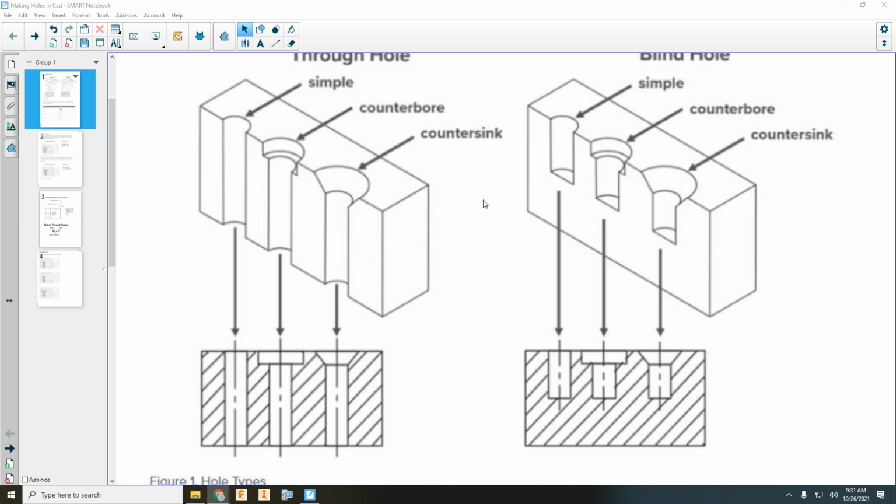Then there are three simple types of holes. We can have a counterbore, which is a flat bottom hole, and you can see that partly in the way our Trammel toy is designed. We're going to get a little bit of practice with the hole notes and measuring because you have some hex head screws and some countersink flathead screws.